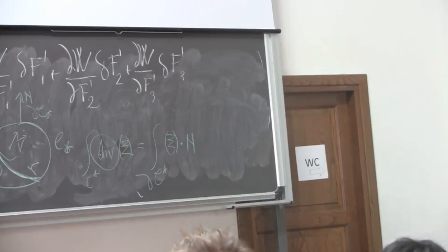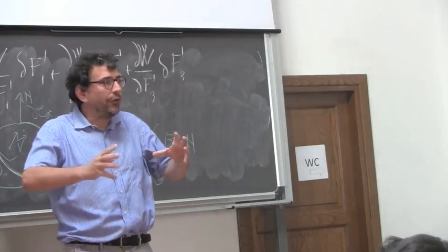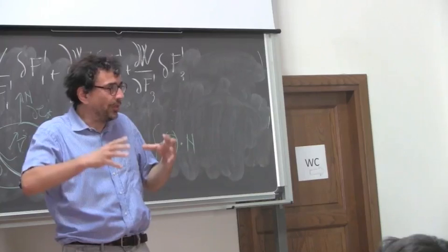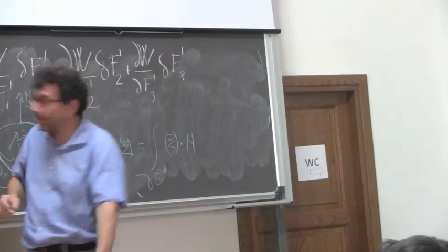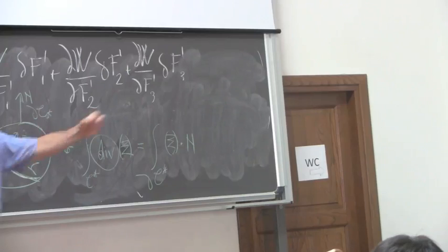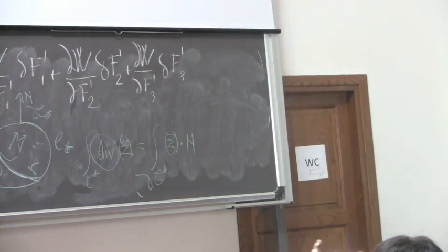Forces per unit area, forces per unit volume. So to a first gradient material, you can apply forces per unit area, tractions, or compression forces or shear forces, forces per unit area, because this n times a displacement integral over a surface is equal to an energy. Or forces per unit volume.